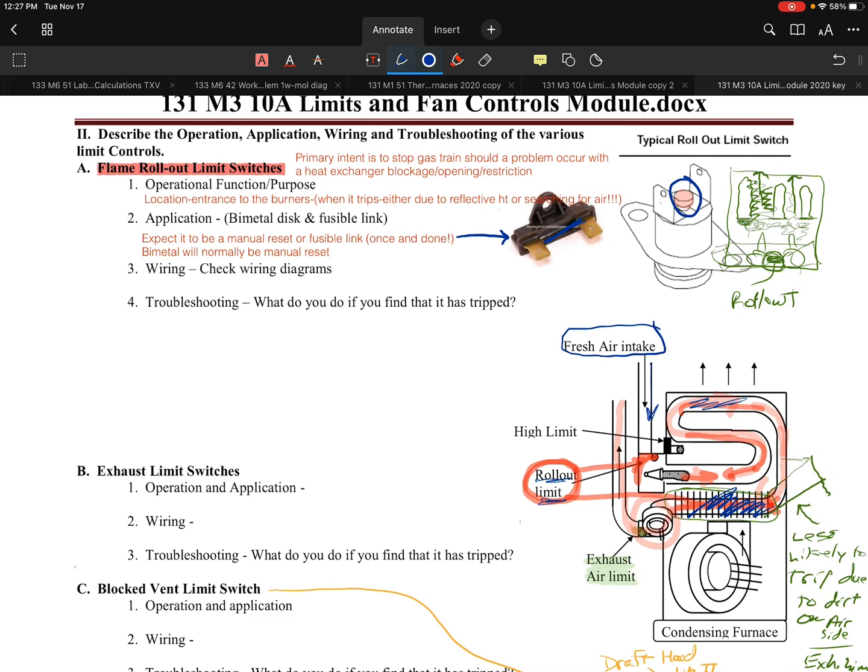What you've got to realize is that if there's any issue, a blockage in here, a blockage in the secondary, or an opening in a heat exchanger like this, you're still going to be putting gas into the furnace and into the burners. However, it's going to say, hold it, what happened to the air? If it can't pull the products through there, this isn't happening. So you're going to have a problem where it's not going to feed enough air into the fire, and once that happens the flame will start looking for it. Typically, it doesn't happen that abruptly. Normally this progresses gradually, and all of a sudden you'll notice the flames will start to waver a little bit.